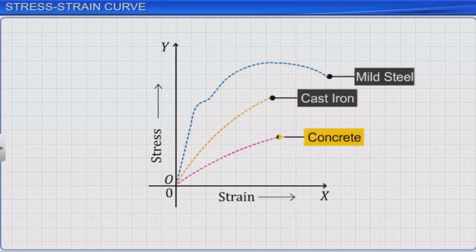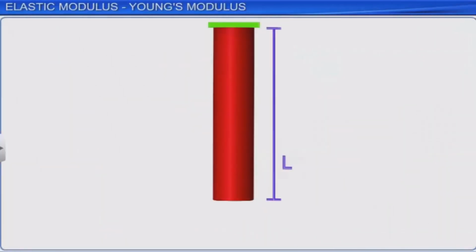So we can say that materials that strain by large amounts before fracturing are ductile, whereas those that rupture at low values of strain are brittle. Accordingly, the study of stress-strain curves for different materials can help scientists identify appropriate material to be used in the design of engineering structures. Consider a solid rod suspended from a rigid support and subjected to tensile force as shown.